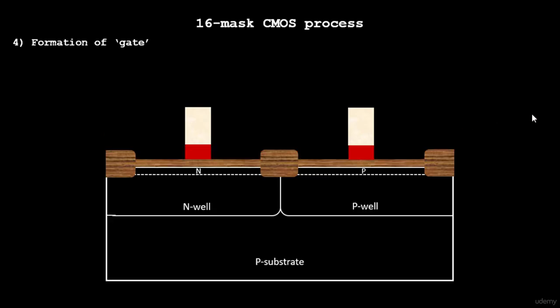voltage. So in our fabrication steps, you try to maintain a doping concentration and an oxide capacitance in such a fashion that you get your required threshold voltage for the transistors, and these are all fabrication steps. That's what is really very important to control here, because these are quite controlled experiments that we are trying to do.